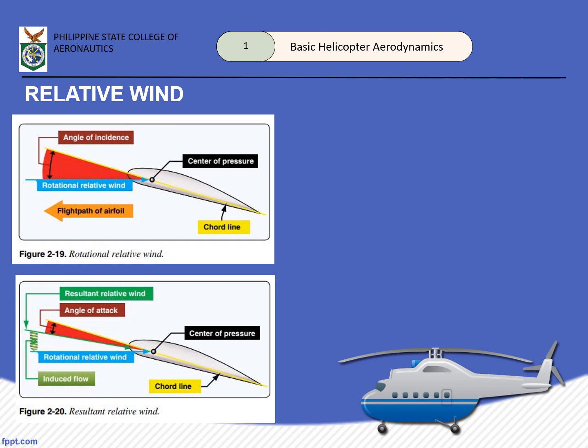This is inclined downward at some angle, as you may see, and opposite the effective flight path of the airfoil rather than the physical flight path. It also serves as the reference plane for development of lift, drag, and total aerodynamic force or TAF vectors on our airfoil.